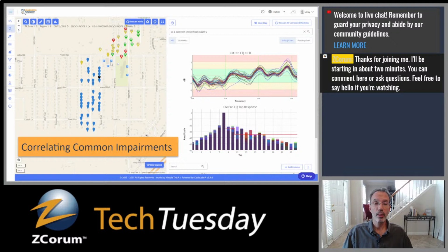So you could see that whatever's causing this problem, if this gets worse and then suddenly gets to the point where one more thing, the straw that breaks the camel's back, you could have all these modems going offline at the same time and suddenly getting lots of calls and trying to figure out where that is. And that's where proactive maintenance comes in. You can look at this correlation group and go, okay, let's try to figure out where this is and fix it before we have an issue that's going to take everybody down, and then we're scrambling trying to fix that rather than scheduling that and taking our time.